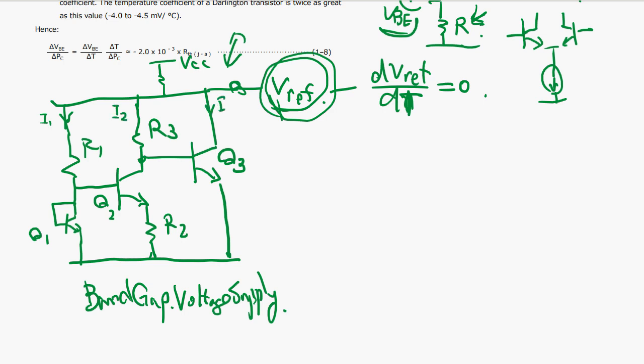This doesn't matter, I3. This voltage VBE, we adjust so that it's the same as this VBE. That means the base-collector voltage is almost zero. Okay, and the currents I1 and I2 are the same.